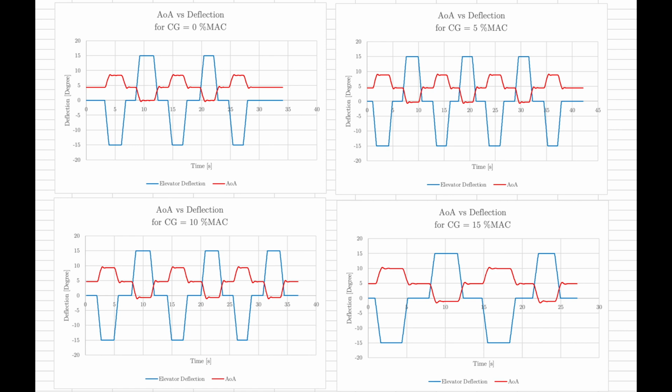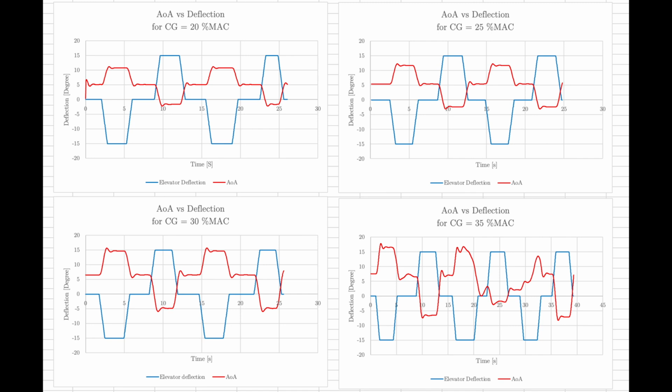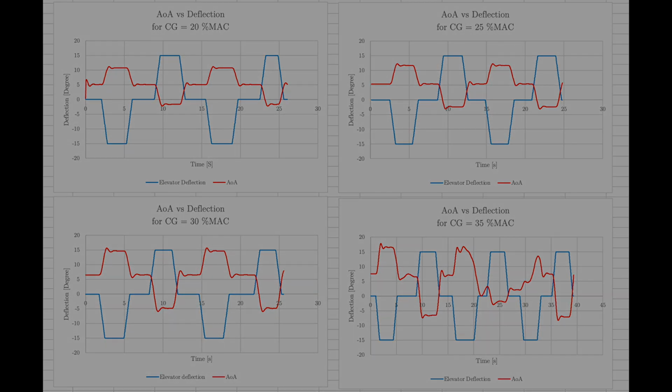The aircraft response became more susceptible to elevator deflection as the CG was pushed aft, because the lower static margin caused the deflection to create a bigger reaction in angle of attack. After a control input with the CG shifted aft, the oscillation amplitude and time to decay of the angle of attack also increased. A right roll behavior appeared when the CG location reached 35% of the mean aerodynamic chord, resulting in extremely significant oscillation in angle of attack as depicted.